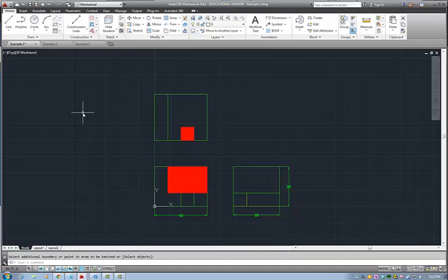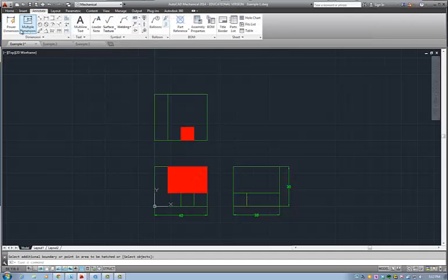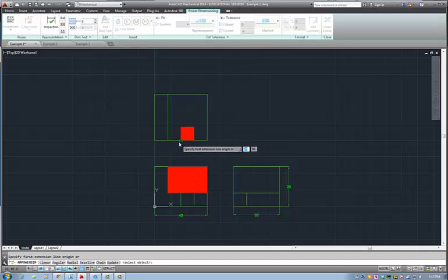And the way that I would dimension these two, I can measure, for example, the width. So for this one it's 10, and for the other one it would be 30. And then the height. So this would be 10 and the other one would be 20. So you see, this is very useful if you would like to dimension what you actually want to remove. So it's very nice for the machining.